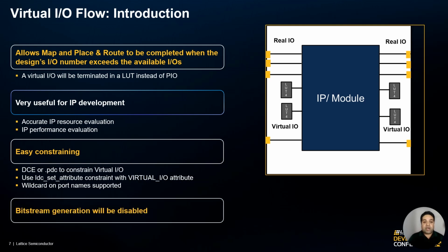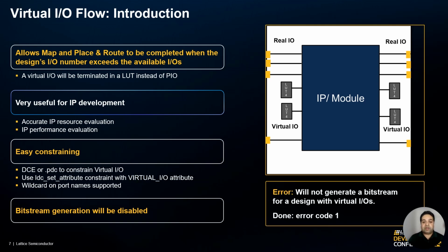Please note, while you're using the virtual IO flow, bitstream generation will be disabled. If you attempt to generate a bitstream for a design with virtual IO, you will encounter an error as bitstream generation is not supported in this scenario.